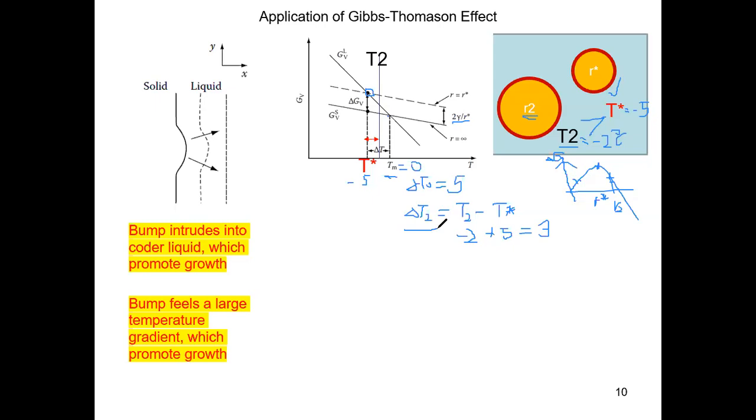So we're going to get the effective melting temperature based on the Gibbs-Thompson consideration. But now we're moving one step forward. Not only do we want to get the effective melting temperature, we also want to get the effective supercooling felt by each particle with different radius. And that is connected to the melting temperature through this very simple relation.